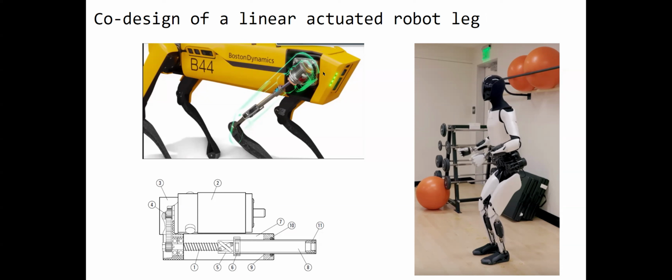It firstly uses the motor as the hip to rotate the leg, but instead of placing these 2 motors with rotation degree of freedom at the bottom, it uses all these 2 motors at the upper part of the robot. What's the idea? If you place heavy parts on the body but not on the leg, it decreases the mass of the leg and hence it decreases the inertia of the leg, which means that reflected inertia of the leg while it's moving on the surface becomes lower, and that means that it spends less energy. The lower the mass and inertia of the leg, the easier it is to manipulate.